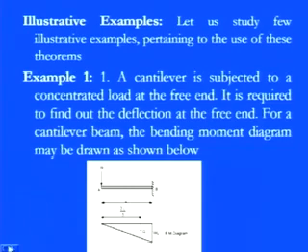So here on your screen you have this cantilever beam, the point load is there, and the total length is L. For that we have a bending moment diagram here. WL is the maximum bending moment, which is there at this end, and here we have a 0. Starting from that, since a point load is there, there is no curvature or parabolic path, a straight line is there. So with this particular section, we have a triangular shape of bending moment diagram, and if you want to locate the centroid, since it is a triangular part, 2/3 of the distance will give you the centroid. So it is 2L by 3, at which the location of the centroid is located in this particular diagram. So you see here we have the required information.